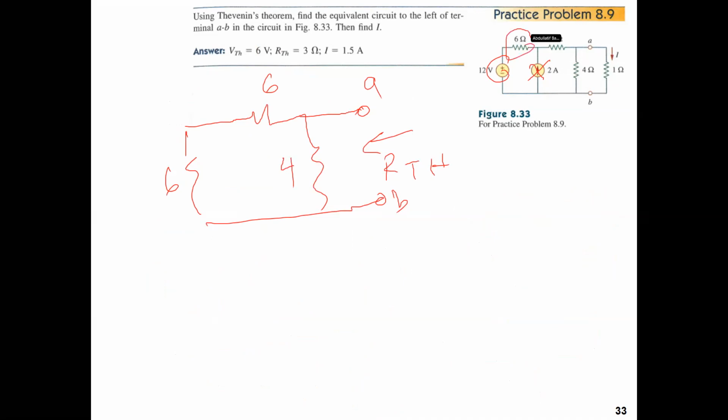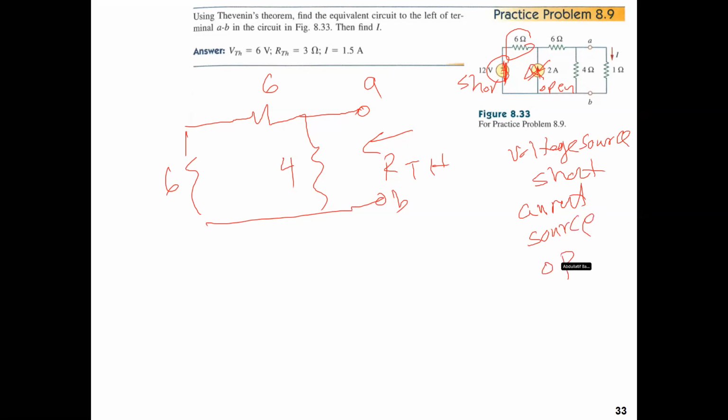This 6 here, let's just turn it around. And this is a short, this is open. Okay, open, short. Don't forget. Voltage source, short. Current source, open.